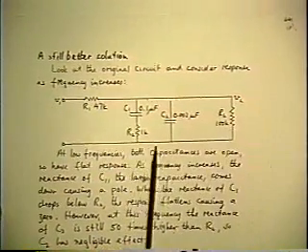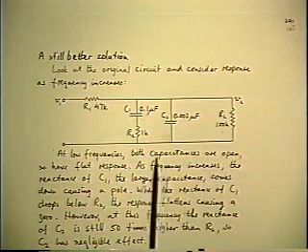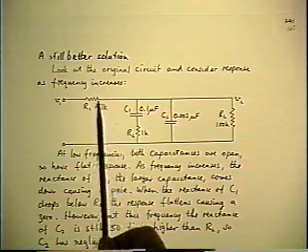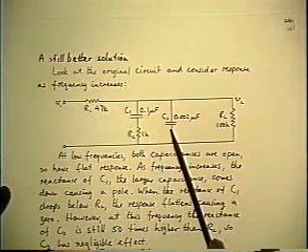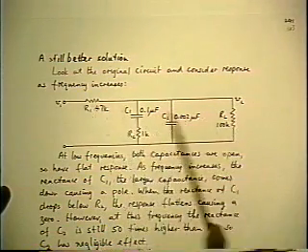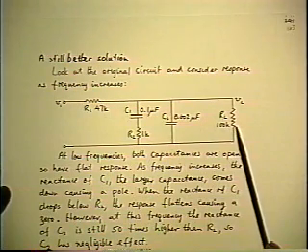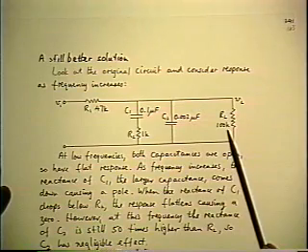Doesn't make any difference. Simply look at the circuit and ask yourself qualitatively what happens as frequency goes from 0 to infinity. What happens is, at 0 frequency, the two caps are open. So you have a simple resistive divider, so you can write down what the 0 frequency flat gain asymptote is. It's just that resistive divider.